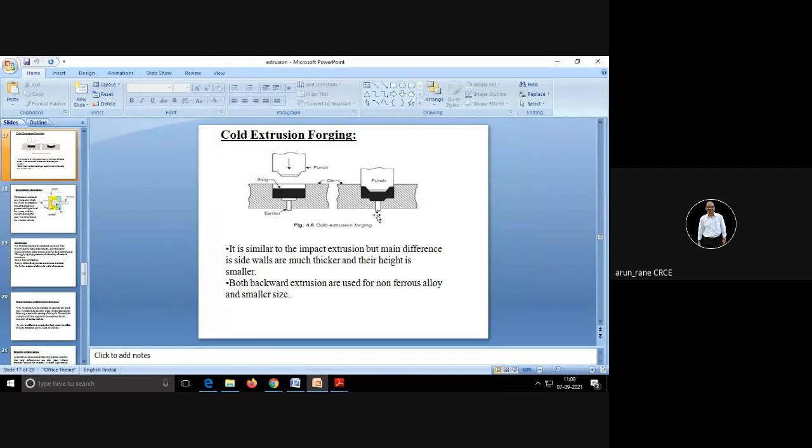So there is an ejector rod which is coming from the bottom. When the punch goes up and there is sufficient clearance between cavity and punch, like suppose this height is 50, as soon as the punch moves more than 50 mm up, this ejector is activated. This mechanism is not shown; it is a part of the press. The moment the punch goes sufficiently high, this ejector rod gets activated. It pushes from the bottom so that the component comes up.